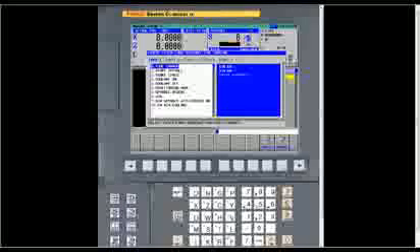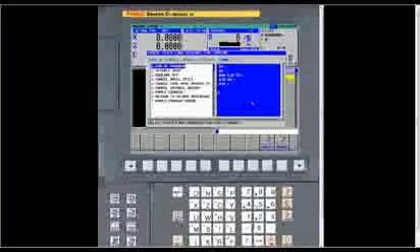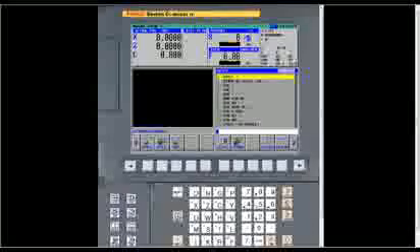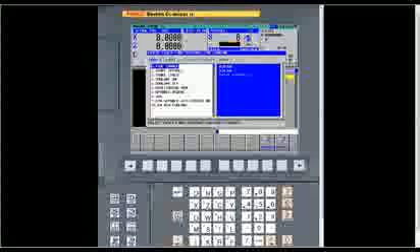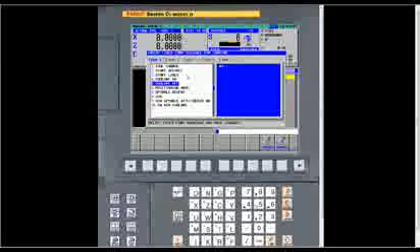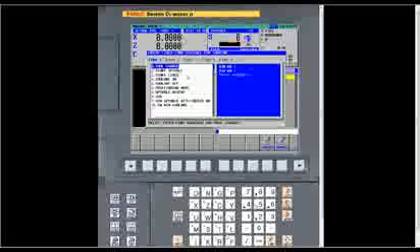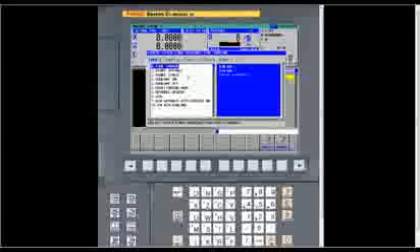different fix forms. And just to let you know, Form 1 and Form 5, they will always be the ones that when you go into start or end, that's what Form 1 and number 5 are. Form 1 will be the start ones. Form 5 will be the end. And what you do, you just go in and set them up. As you can see, I've got tool change, start spindle, start lines, tooling on, whatever you want to put there. You just set it up however you want.